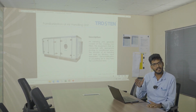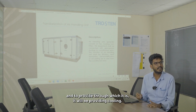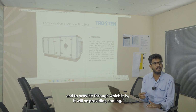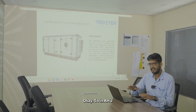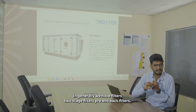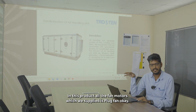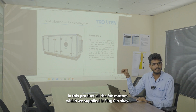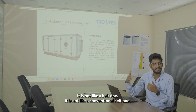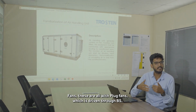The AHU's purpose is to recirculate the air within the building spaces and provide cooling. Generally in an AHU we have two-stage filters, pre and back filters, then cooling coils, then fan motors. In this project, all the fan motors we supplied are plug fans. They are not conventional belt driven fans. These are plug fans driven through VFDs.